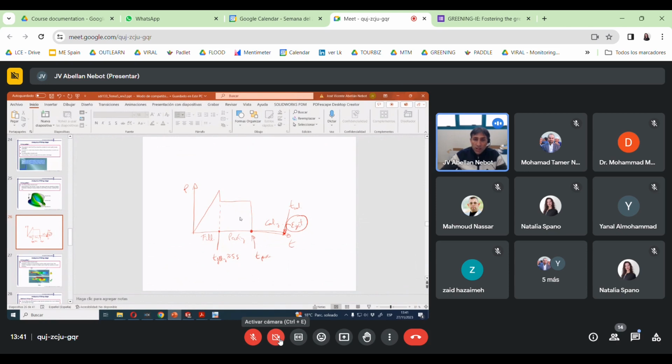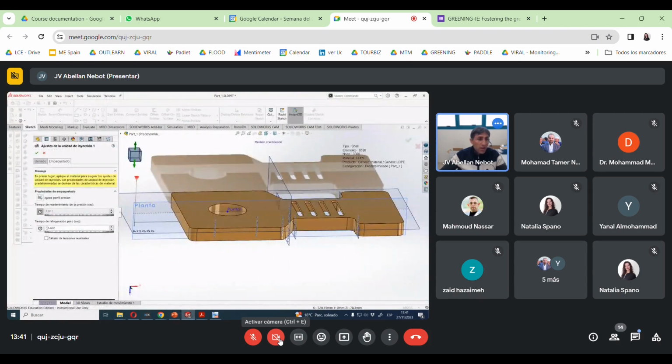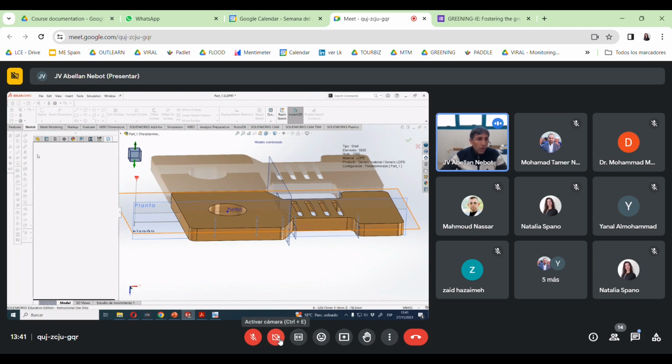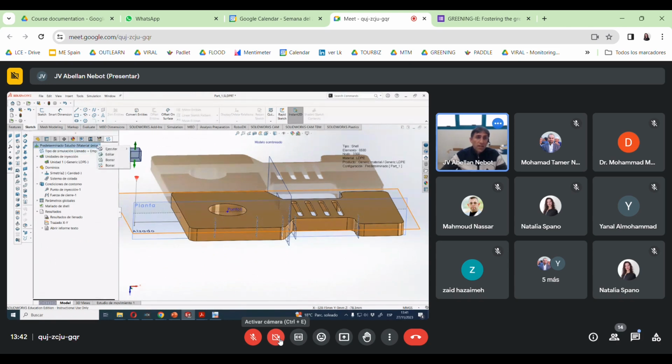And then after packing, we are not going to apply any pressure, but we still clamp, we still keep the mold closed, until 31 seconds. You see, this is the cooling time. And after that, we will eject the part. Okay, that's the idea. So this is according to SolidWorks. Okay, fine. So let's see what happens with this analysis.